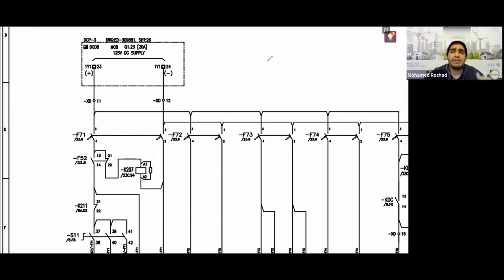However, in the case of a long run time, as we saw earlier, the trip relay will activate and open the MCB F52. Once it opens, I have taken a normally open contact from it and at the same time a normally closed contact. Of course, the terms normally open and normally closed refer to the MCB, which is originally depicted in the open position, right? So now let's say the MCB was closed. So this is closed, right? And this is open. If a trip occurs to this MCB due to the long run time, the status of your contacts will be as you see in front of you.